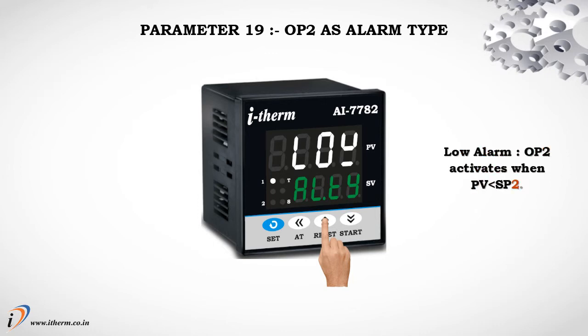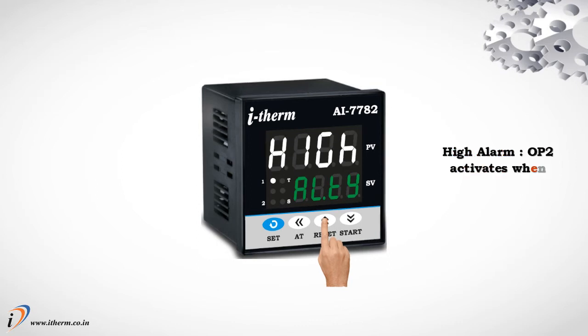Low alarm. Output 2 activates when process value is less than setpoint 2. High alarm. Output 2 activates when process value is greater than setpoint 2.